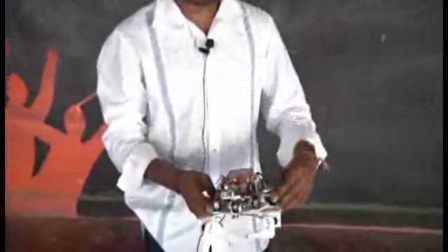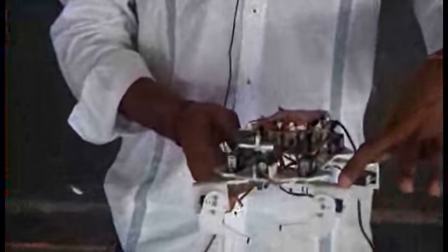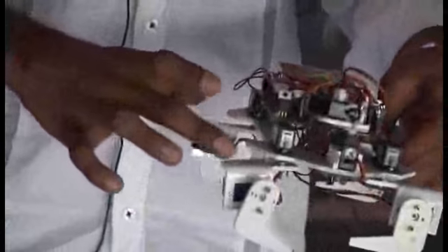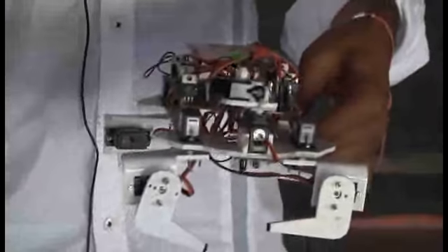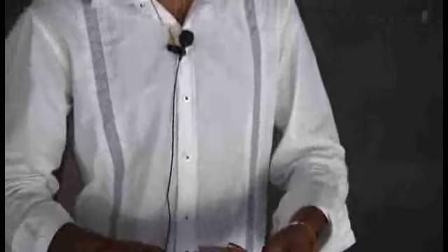So in this case, the R and the theta value that it generates are used for generating parameters for it to follow the object. Generally the left thighs are controlled with a parameter called U, and the right thighs are controlled by a parameter called V. So R and theta are manipulated in such a way that we get proper values of U and V so that the bot itself decides what radius of turn, how many steps and what turns it has to take in order to reach the object. So that is the searching algorithm.